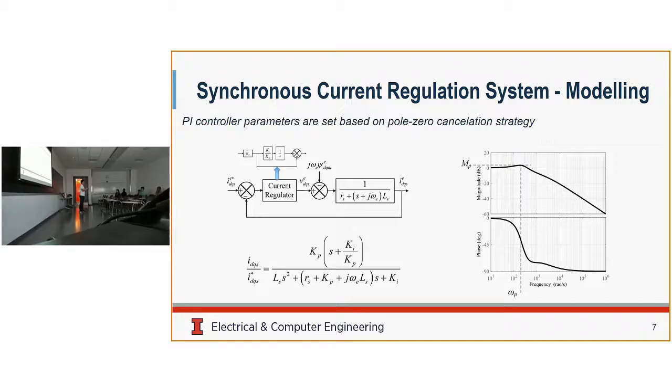But then is this cross coupling? Ultimately you're going to pick Id and Iq separately such that j omega e doesn't exist, because those Idq are also imaginary quantities. So these two are vectors, right? They have a real part and an imaginary part. So when you have this transfer function, for a certain sinusoidal input excitation, you replace s with j omega.